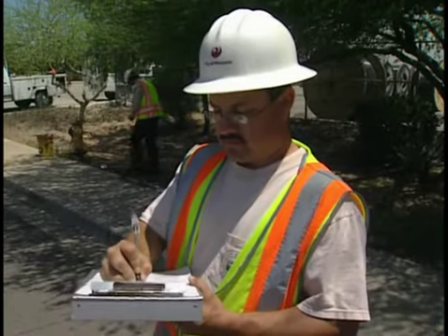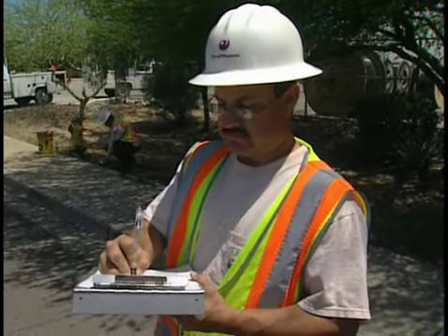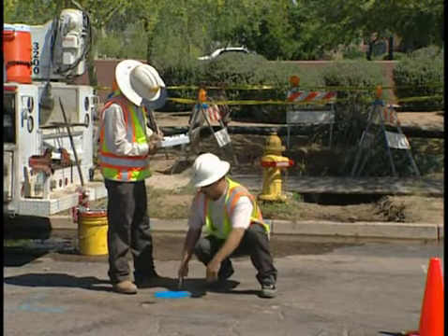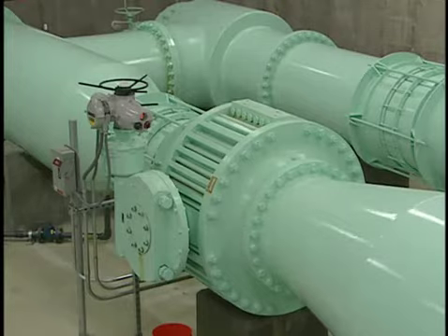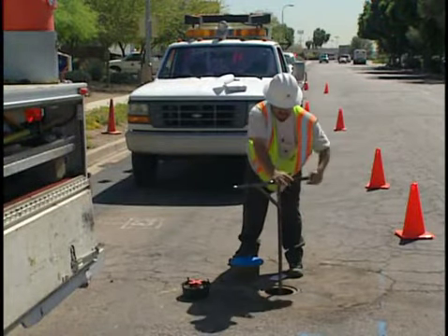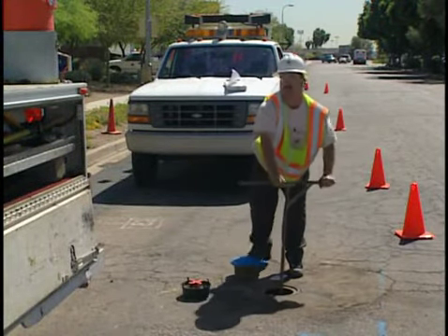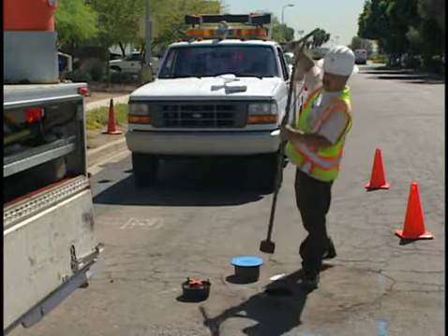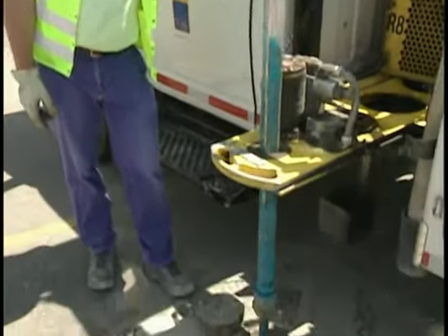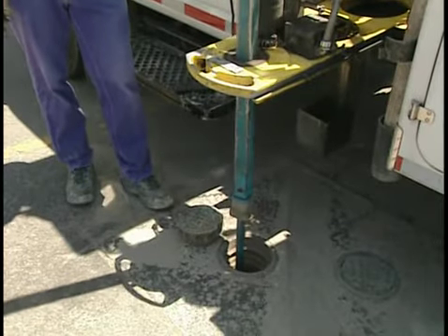Here are some general guidelines for a valve inspection and maintenance program. Inspect each valve on a regular schedule, annually if possible. Inspect 16-inch or larger valves more frequently. Inspect the valve box or vault. Cycle all gate valves from full open to full close and back to open at least once every 2 years. Some valves require less exercise, so follow manufacturer's guidelines.